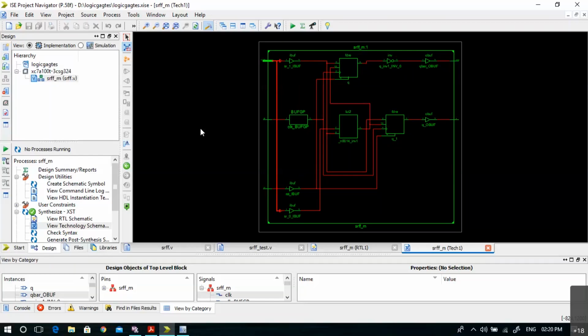The reason why the flip-flop is present in the library by default is that a flip-flop is a normally usable electronic block in all our electronic hardware, right? So each time we write code for a flip-flop, it need not generate other circuits for it using the gate primitives. As such, a flip-flop can be stored in the library and it can be accessed anytime by the synthesis tool.